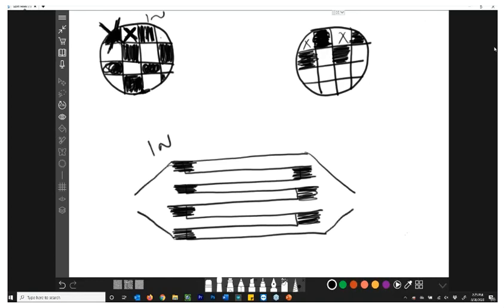Now, if this was the inlet of the DPF and this was the outlet of the DPF, here's what happens. As you're driving, exhaust gas comes into your DPF assembly. Now, it can't go here, obviously, because this is blocked off, and it can't go here because this is blocked off, and the same goes for this. It can't get to these chambers. So it's going to have to go to a chamber that's open.